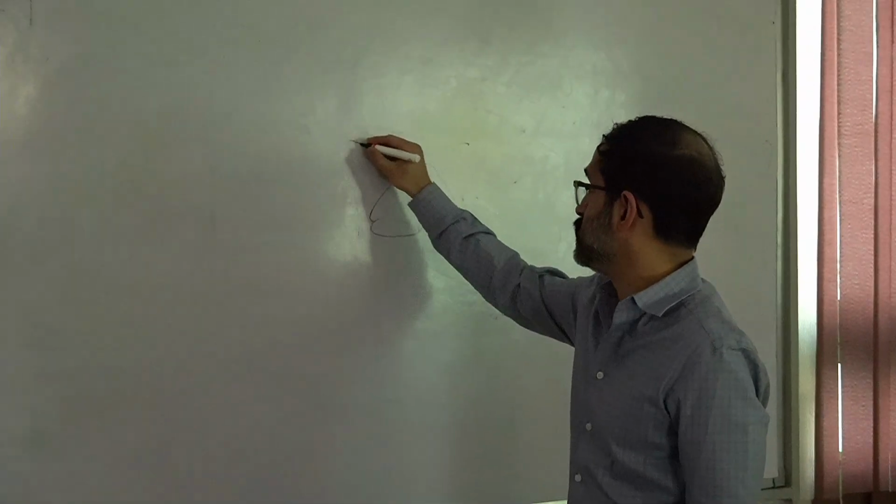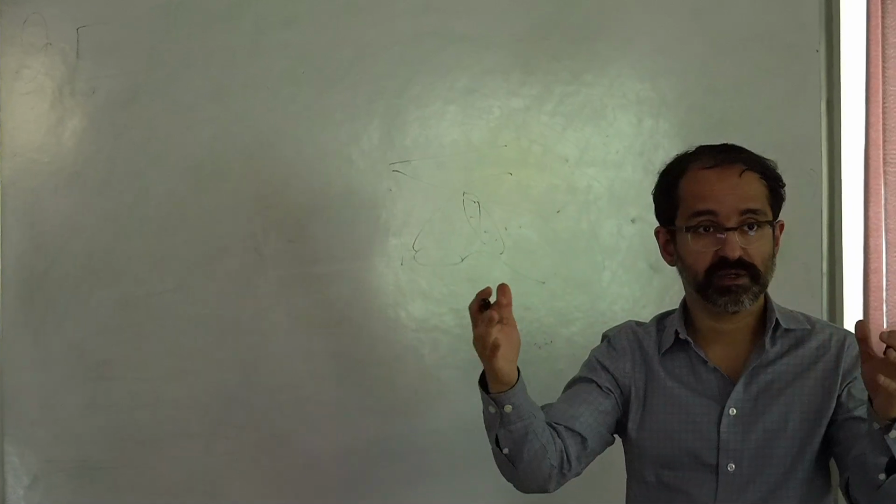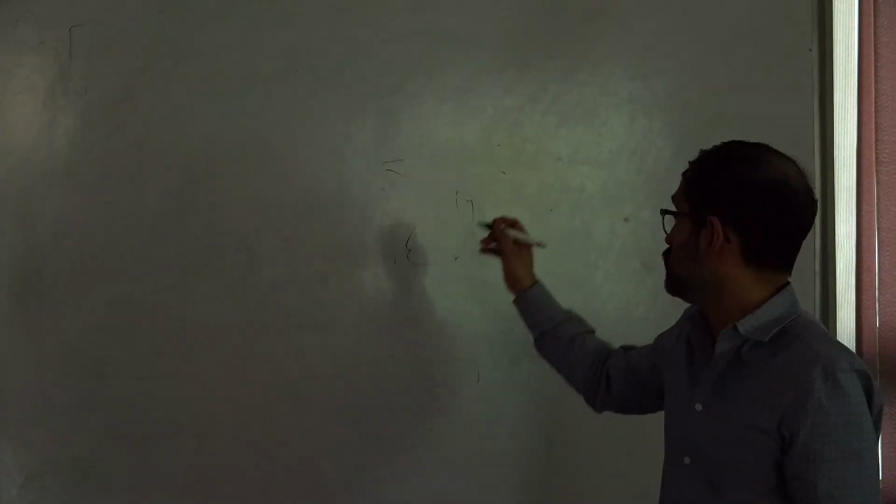But if you are trying to use the same geometry for 3D printing, you need to make sure that the hollow space remains. If you just print this, it would become a solid model. So then we have to figure out a region, or basically a storage container, which would contain that cavity. And that's what I did.